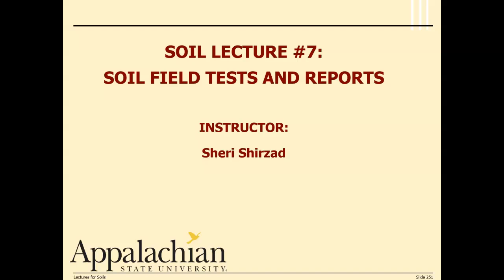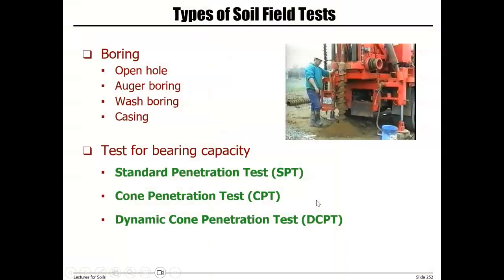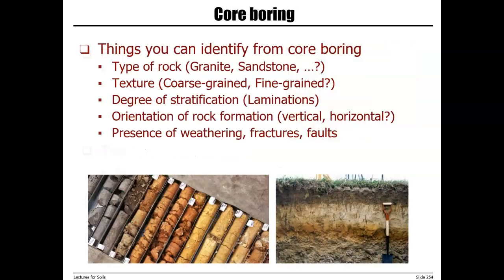Lecture number 7, Soil Field Tests and Reports. So there are different boring techniques that are used for soil testing: open hole, auger boring, wash boring, and casing, and three main field tests: a standard penetration test, SPT, cone penetration test, CPT, and dynamic cone penetration test, DCP.